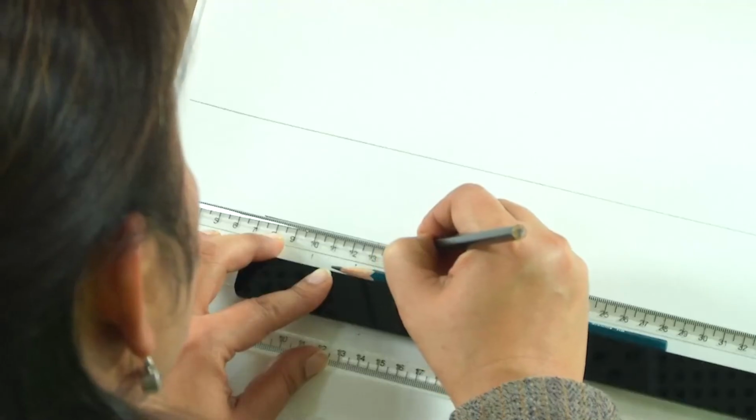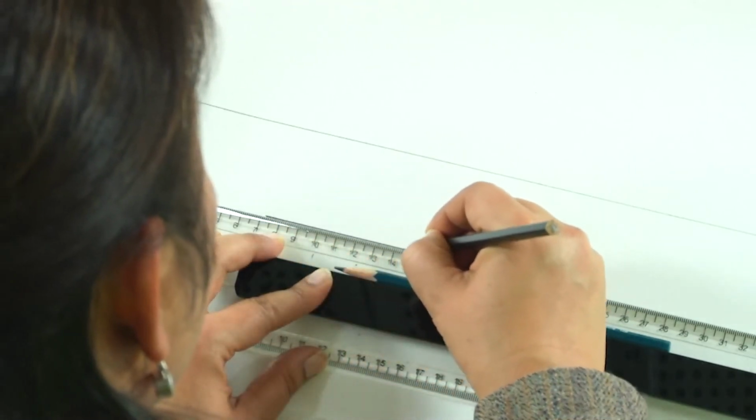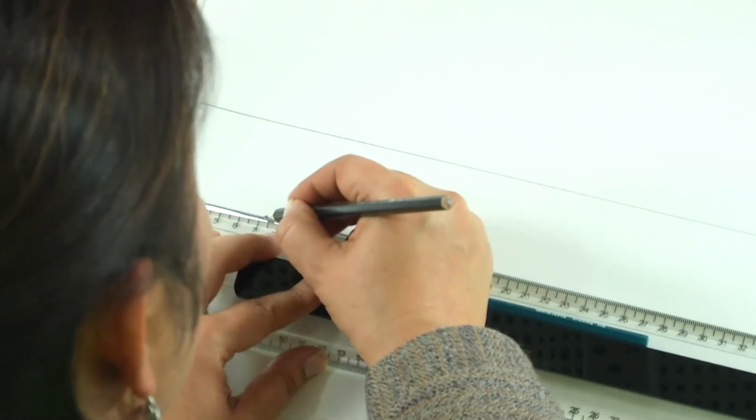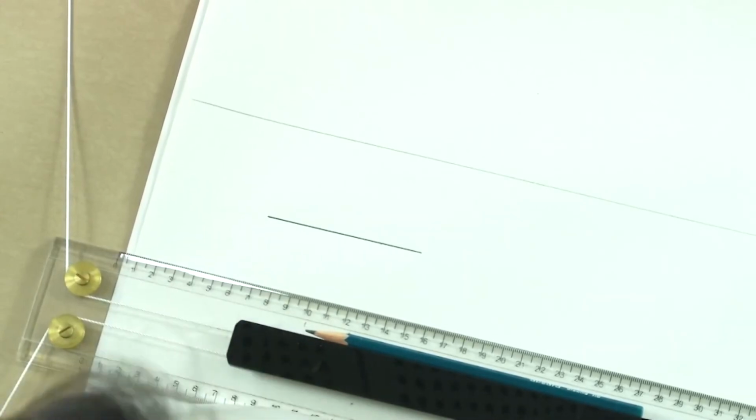So we will darken this line. We should always be careful about the thicknesses of the lines that we are going to be using. So for darkening, I have used a 2B pencil. Ideally, we should not be darkening directly. You should always draw the entire drawing in light pencil, say 2H first. This is 2H in my hand.